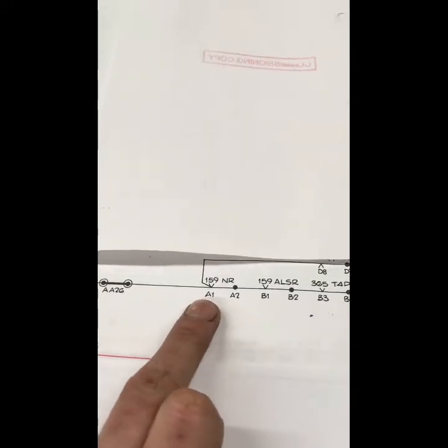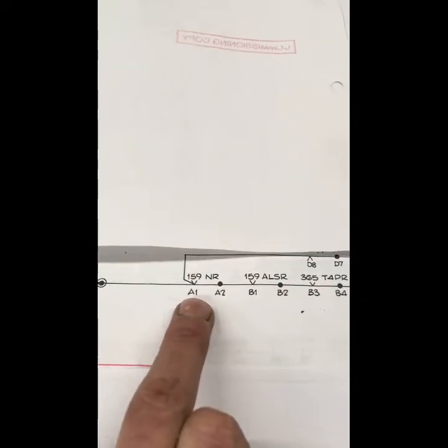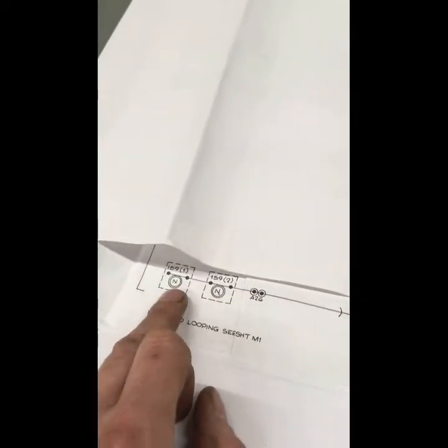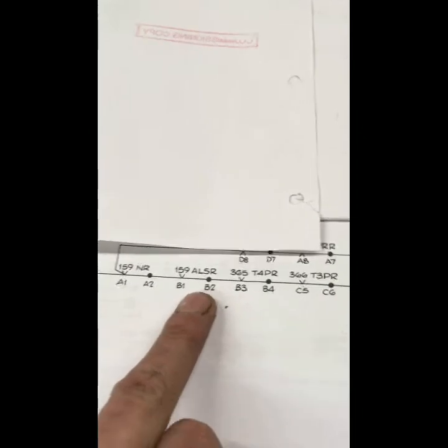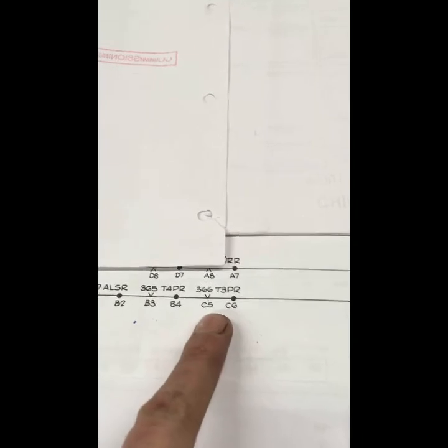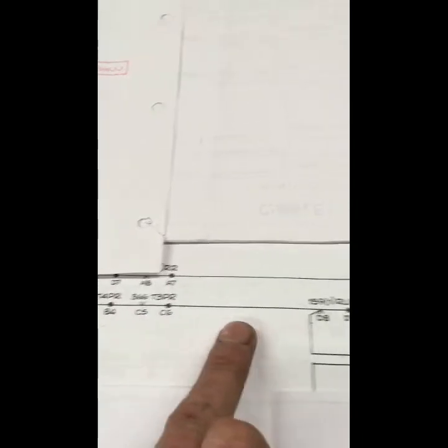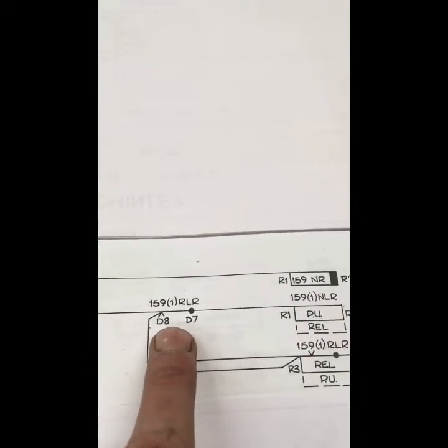Following it through, our normal NR is up, because we haven't cleared that yet, that is still in the normal. Our NR is up, we haven't cleared the signal yet. We're free of approach locking, and our track circuits, that concerned circuits, are up and clear, not occupied. Moving along, we have not yet put the signal to reverse, our lever to reverse, so our RLR will be down. Our normal latched relay will therefore be energised, picked up.